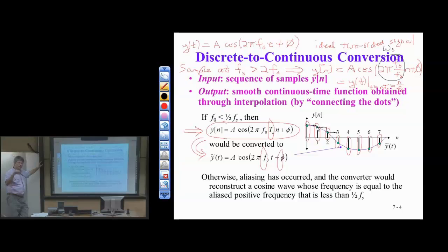But you'll pick up the original square wave and all the harmonics up to half the sampling rate. And any harmonics above half the sampling rate will get attenuated by the analog low-pass filter before sampling. So you'll get the fundamental frequency and a certain number of harmonics. Okay, so lots of ways I can do this.